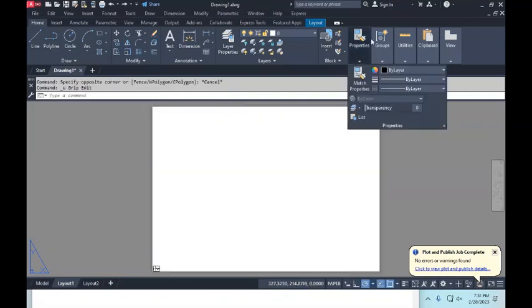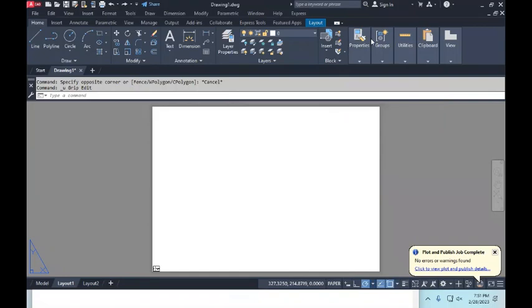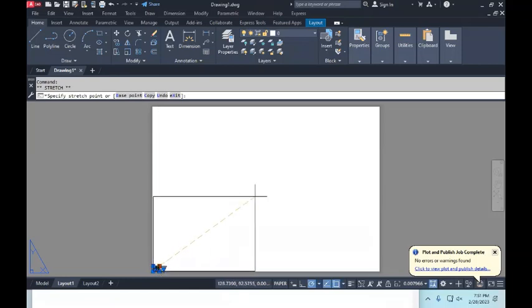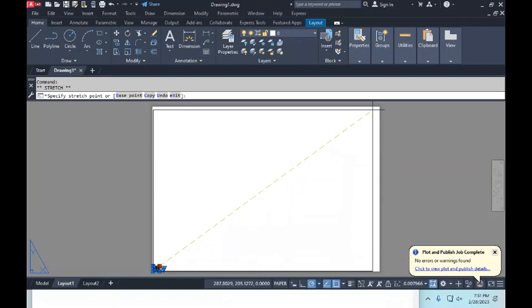I'm going to repeat that again. So after you hit apply to layout and hit OK, close that dialog box for the printer. Then you come to this right at the corner. Select that. Okay, and then hold one of the corners. When I say hold, click on it. While keeping the left button of the mouse clicked, hold, press and drag it out. And then release, or you can click once again. Right. That's what happens.